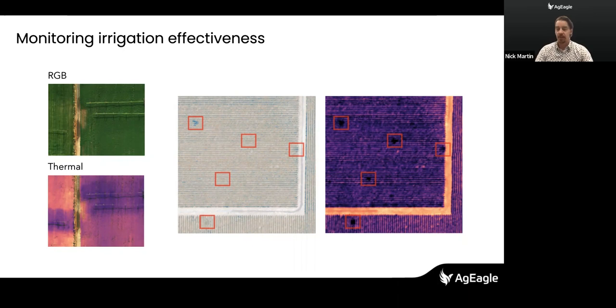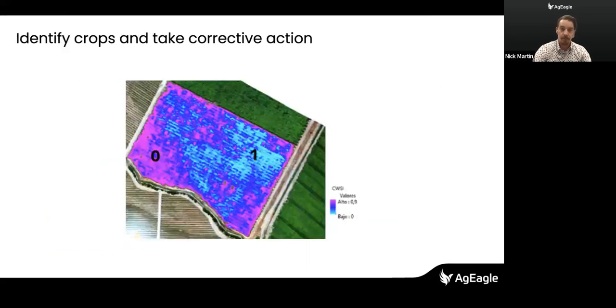Multispectral sensors are able to determine the differences in temperatures, and you can then surmise what's happening there in the field. If you have a flooded area of the field, it will appear colder. So is water pooling? Is there water leaking from a center pivot irrigation system? This is the intention of flying our sensor over a field. It's all about what you know.